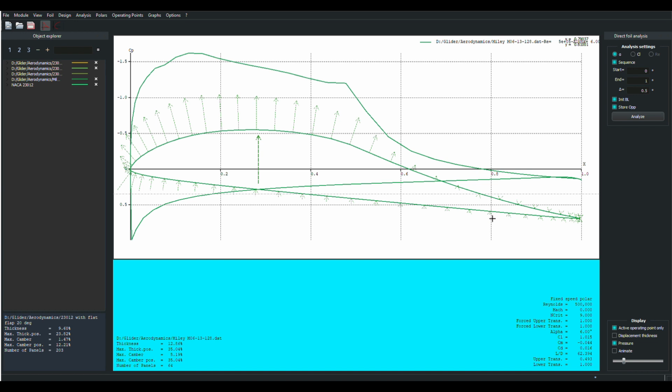And they're relatively thin back here. They chose a spot. They needed a certain amount of elevon area, and they only have a certain amount of span, and they got some flap on there. So they made the span of the elevons the maximum that they could, and then the chord of the elevon just drops out of that little calculation, and it says, oh, it needs to be about this big. And that just happens to be where this pressure reversal occurs, which, as we've seen, is very handy. Handy dandy.